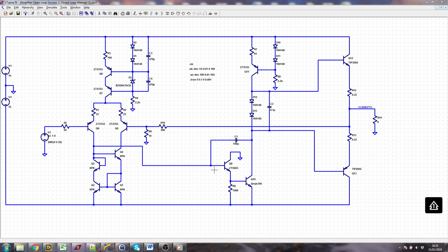0.7 is a lot for a transistor. Conduction will start at about 450 millivolts. By about 650 millivolts it's good and turned on, and by 0.7 it's well into turned on hard, and by 0.8 or 0.9 it's blown up.